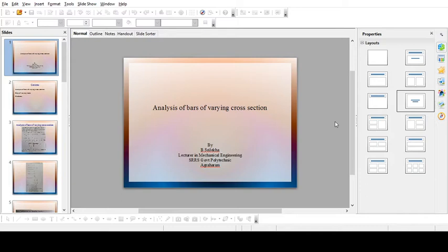Next, the stress induced. Stress is nothing but load by area. So the stress induced initially, sigma 1, is equal to load by area of the specimen, that is 80 into 10 to the power of 3 by 400 pi. If you calculate this, you will get a value of 63.66.